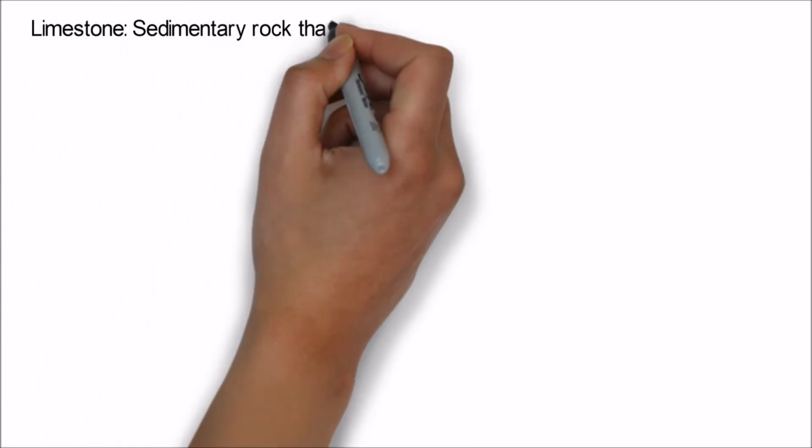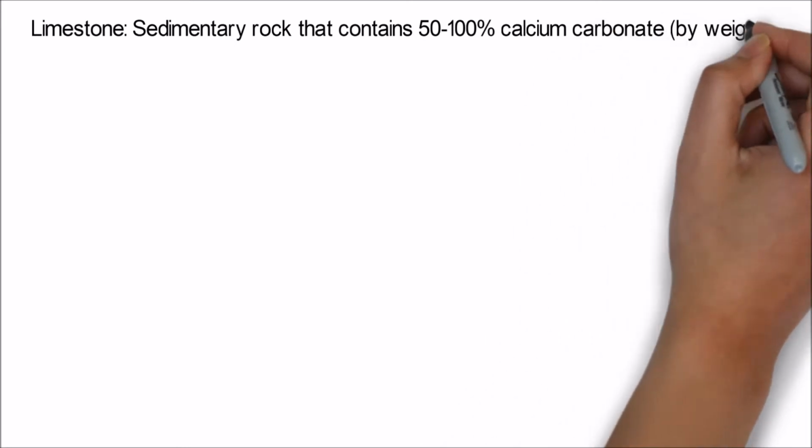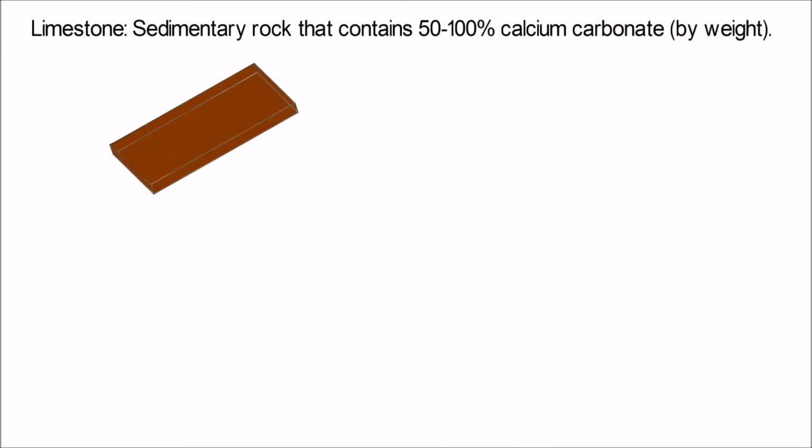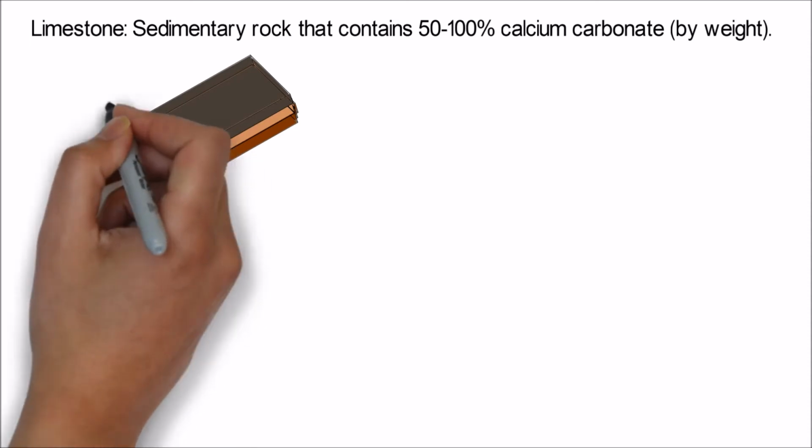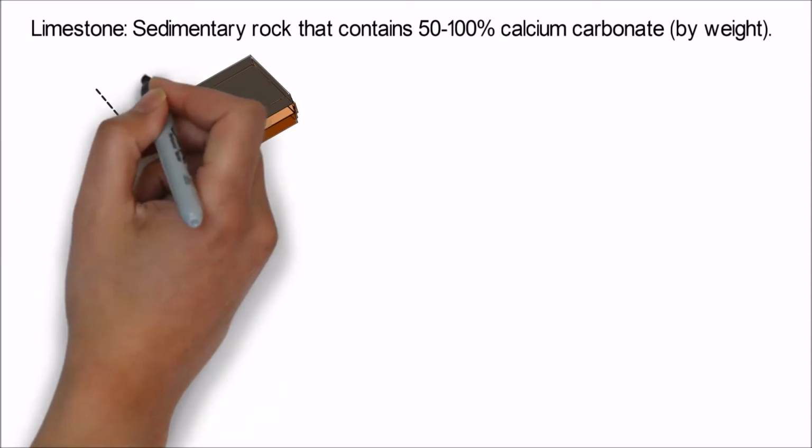The composition of limestone may vary. Therefore, in order to maintain compositional consistency, the limestone is pre-blended. One method of pre-blending is to stack the material in the longitudinal direction and reclaim it with a transverse scraper.